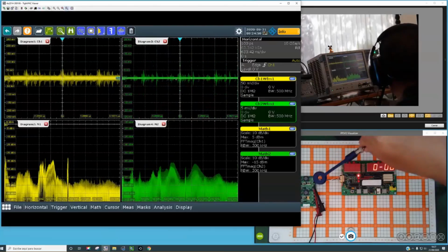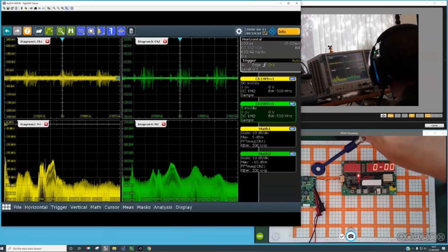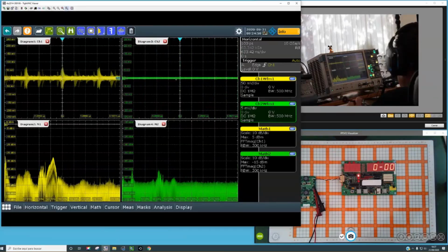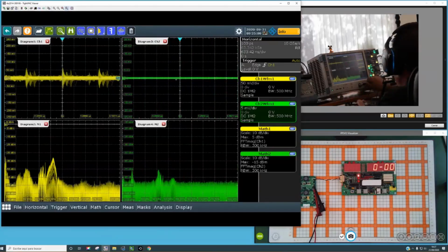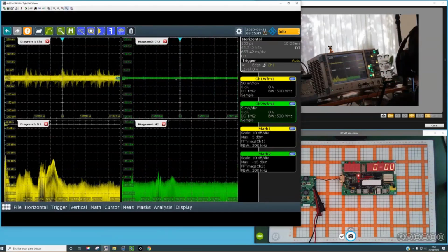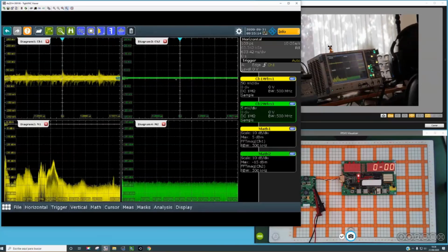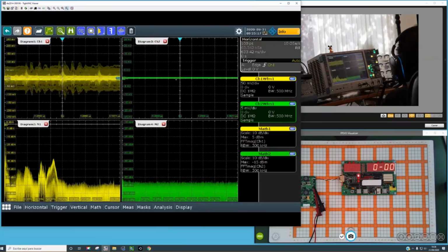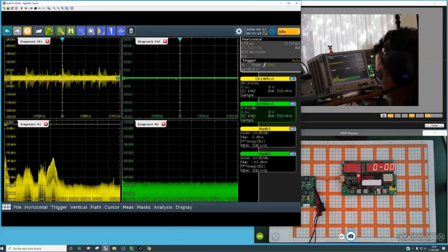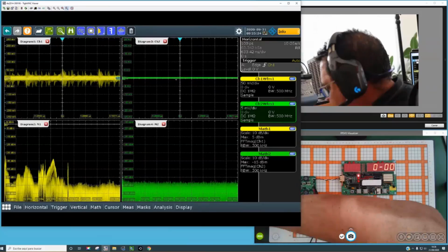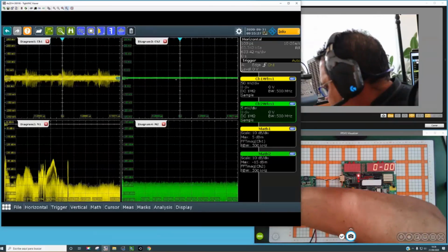Obviously, many people, and I am working with near-field probes many times, find in this tool a very, very good instrument to understand or to solve EMI problems. But let's switch to the EM scanner. What is the EM scanner? As I have explained previously, I will start with the flat scanner. The scanner is connected to the spectrum analyzer and is connected to the computer with the software, the EM viewer software. So let me connect the output of the scanner to the spectrum analyzer, the cable, okay.